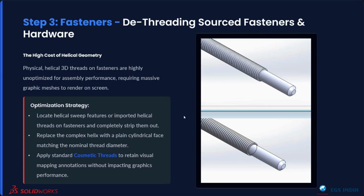You can also define a callout over here, etc. All of this can be called onto your drawing sheet automatically. So instead of having the physical helical cut within your top level assembly, you can have just a representation of it, where it is almost zero graphic angle and zero resources required for it.